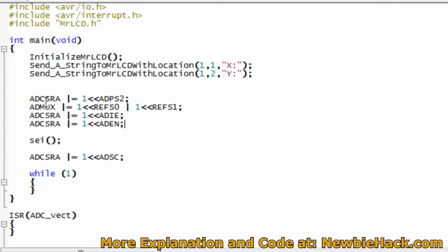And generally what I would do is it's under the ADMUX, and it's the last 5 binary digits of the ADMUX. It's from 0 to 4, the ADMUX register. And here I would just put in an OR and then the channel, which let's say we start with 1. We just put a 1 there.